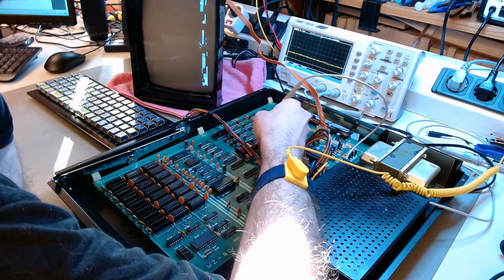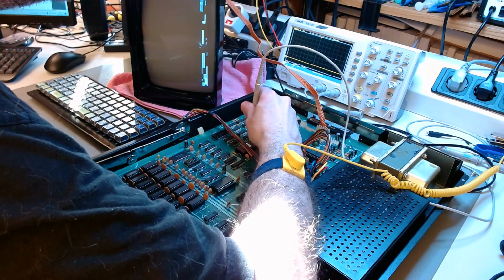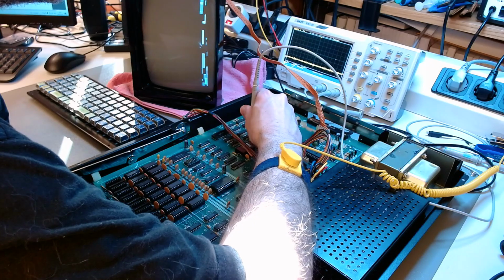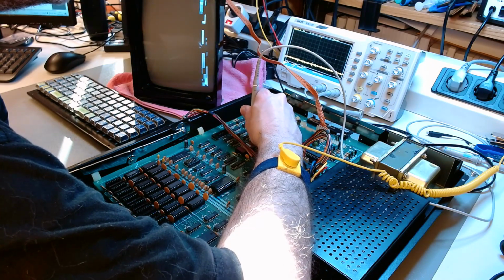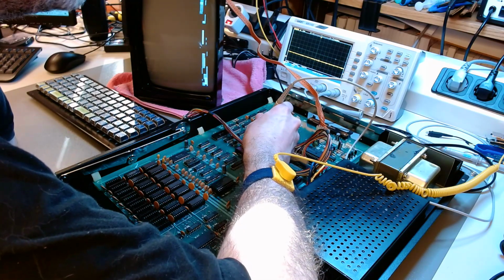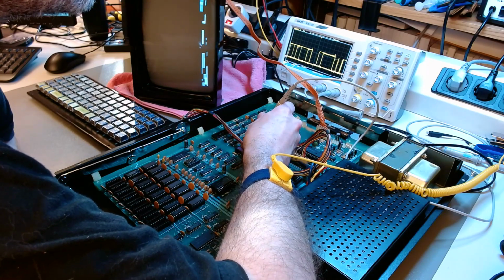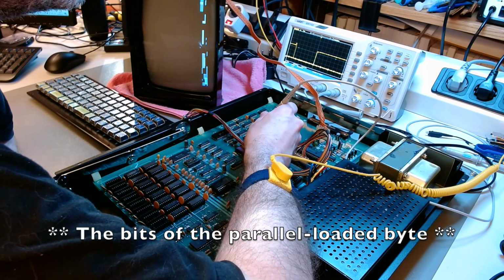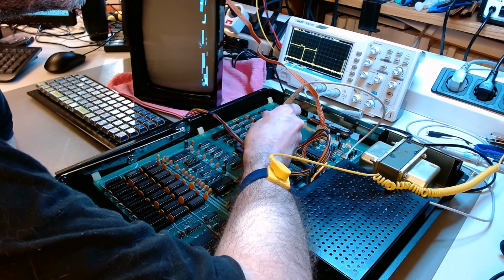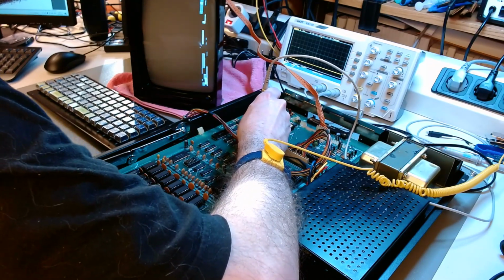Let's look at the other clock input, which can also be used as a clock inhibit if it's high, and it's low, so it's not inhibiting the clock, but there is no clock coming in. That line is floating. Let's have a look at the rest. These are the parallel loads. Yeah, that looks okay. Yeah, these are the parallel bits that come in, and they all look as they should look.